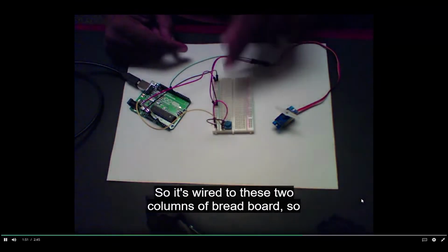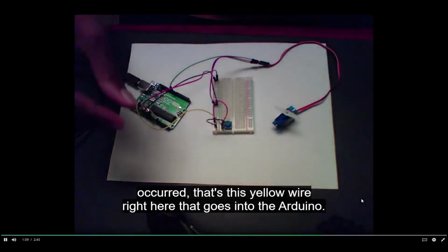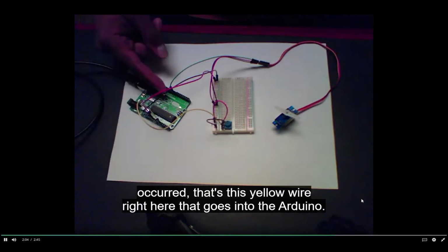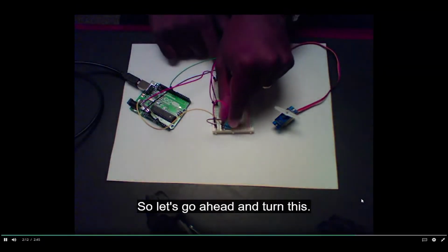So it's wired into these two columns of breadboard, so it's also wired to the potentiometer. The potentiometer's output signal reports how much rotation has occurred. That's this yellow wire right here that goes into the Arduino. And then there's a green wire from the Arduino into the servo, which controls the angle to which the servo is turned. So let's go ahead and turn this.